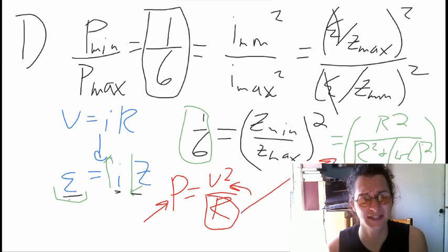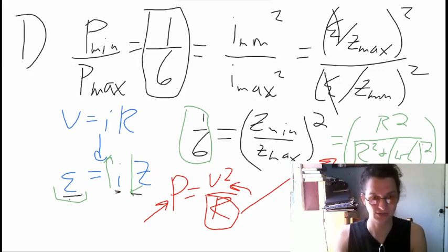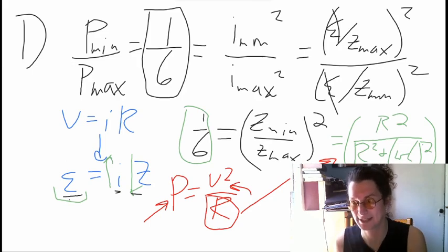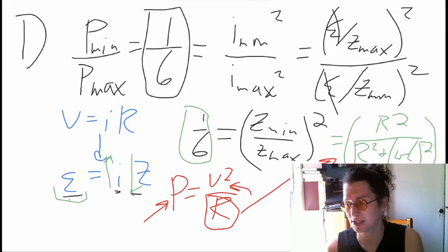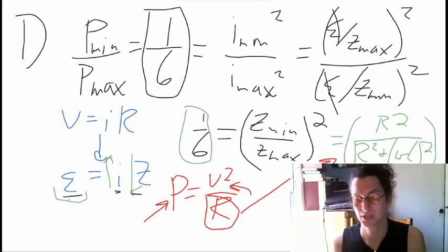The omega given is just the frequency given for the electrical supply. Keep in mind that frequency is given in hertz, so you need to multiply by 2 pi to get omega, but then you can plug that in as well, 2 pi times the frequency given, and then you can solve for the inductance in that problem.